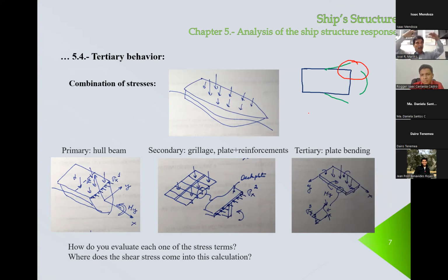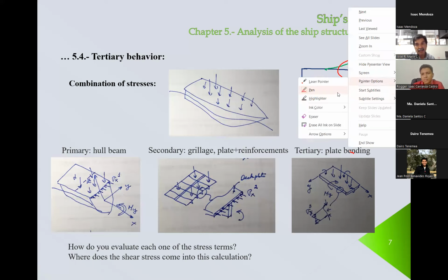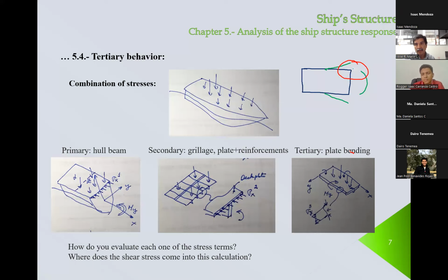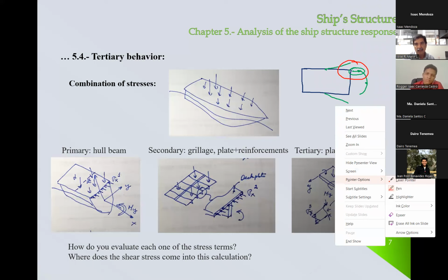So in this area, we are quite away from the neutral axis, so the normal stress will be very high. And also, you see that in this area, the shear stress is important. See that this value is important. The maximum does not occur here, but it's not that small. In the central part of the section of the deck, that's something that Ms. Santos was asking me.